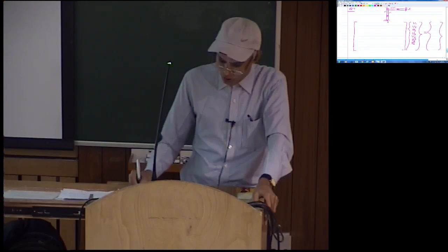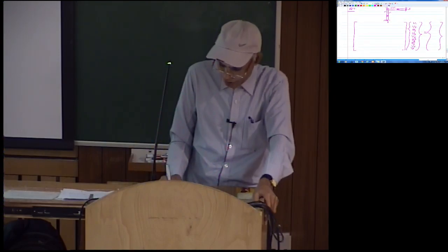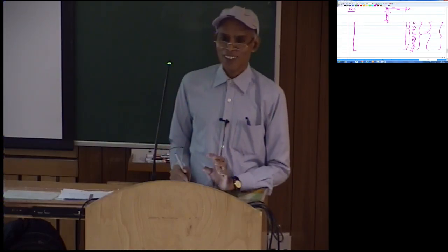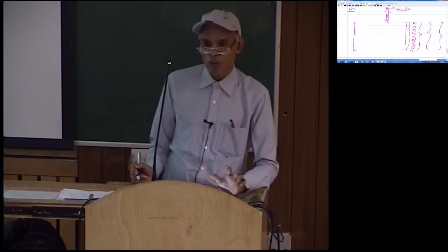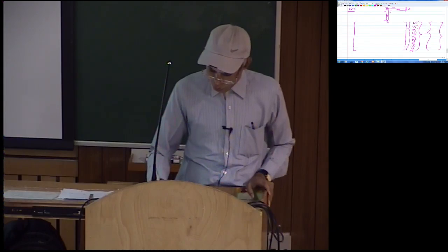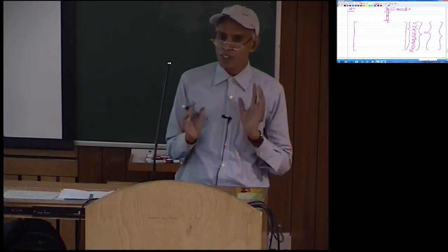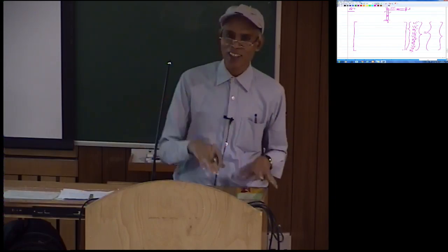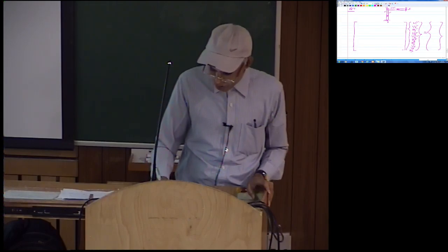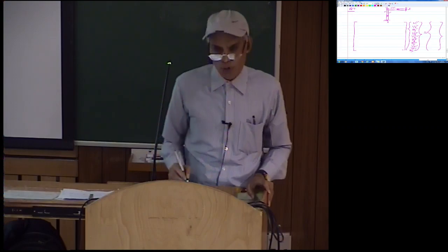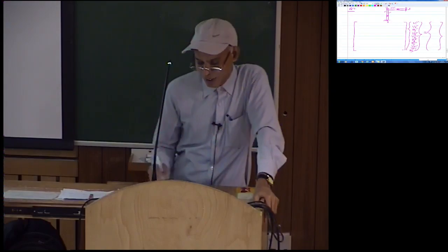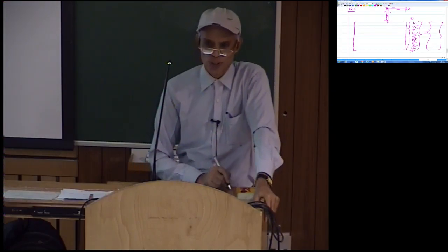And then of course the third node, which is U3, V3 and theta 3. So now your stiffness matrix is going to be, rather than 9 by 9, actually 10 by 10. The first element contributions would go to the first 6 rows and columns, whereas the second element contribution will go to the 4th, 5th and then 7th, 8th, 9th and 10th rows and columns, in the corresponding rows and columns, same thing on the right hand side. So this is what I expected in this last question.